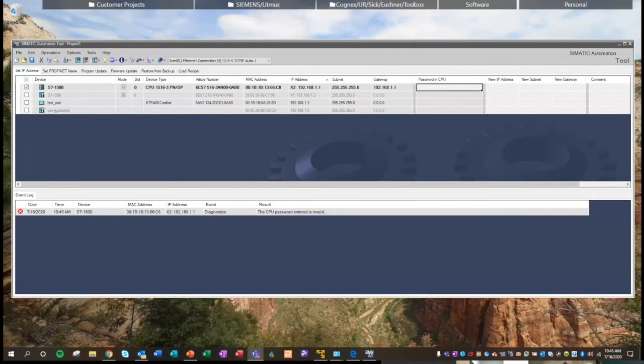While we're here, I'll show you what I was talking about with the diagnostics functionality in the Simatic automation tool. Let me pull this up. Sorry, I've got like 20 windows open. All right, so here's all my devices. And this is what I meant by that, Carter. If you were to use TIA Portal to work with maintaining or looking at your PLCs, to work with the S7-1200, you would need Step 7 Basic licensing. If you would work with the 1500, you would need Step 7 Professional licensing. With the automation tool, you have the option to do all of the maintenance functionality without having to purchase two separate license levels. You can just purchase the basic licensing for the Simatic automation tool, which is like a couple hundred bucks or something like that.